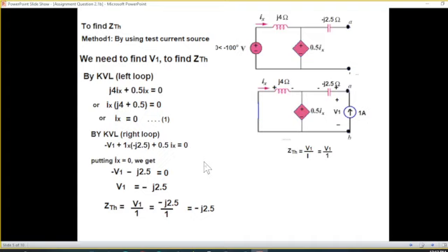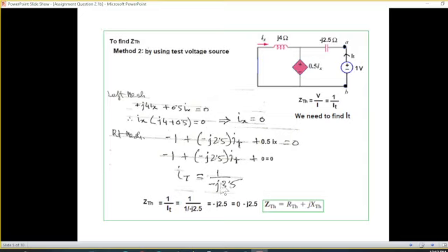So now this circuit will be the Thevenin equivalent circuit. Okay, one more thing, just to clarify: I'm writing impedance in this form, that is R plus jX. That is why I have added a 0, showing that the Z Thevenin is 0 minus j2.5. And so that was the answer.